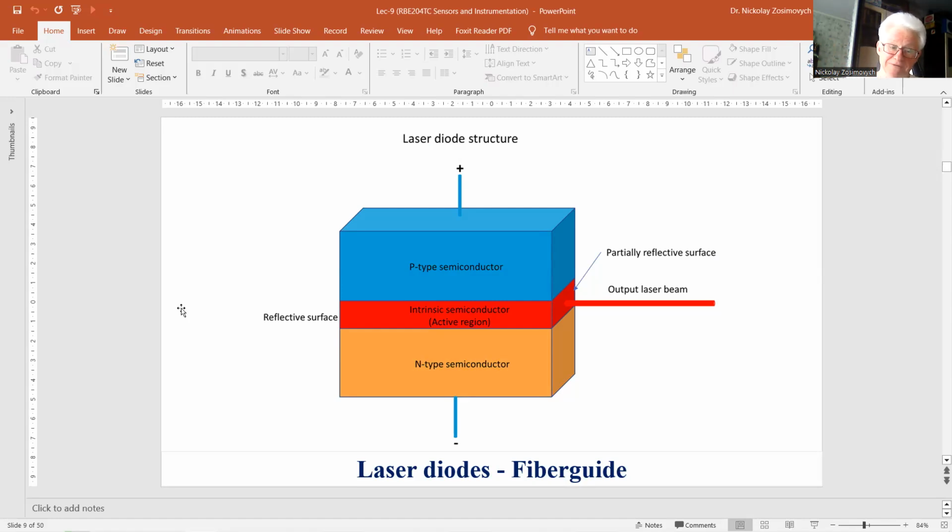Laser stimulation by injection of charged particles. Electrically controllable intensity, monochromatic, meaning a very narrow spectrum, generally a few nanometers, covering most colors in the visible spectrum, infrared, and near ultraviolet, based on gallium nitride. Moderately focused beam, same as LED.